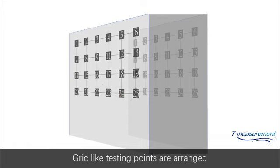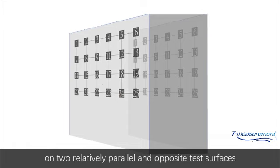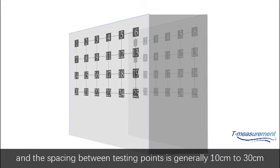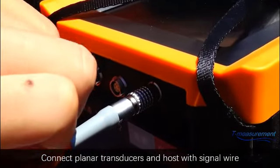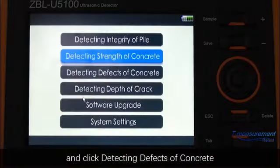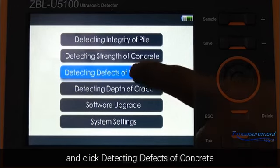Grid-like testing points are arranged onto relatively parallel and opposite testing surfaces, and the spacing between testing points is generally 10 cm to 30 cm. On-site test. Connect planar transducers and host with a signal wire, and click Detecting Defects of Concrete.